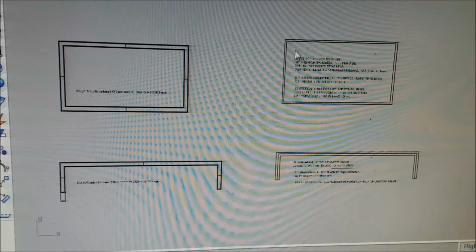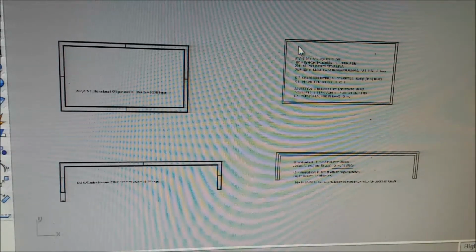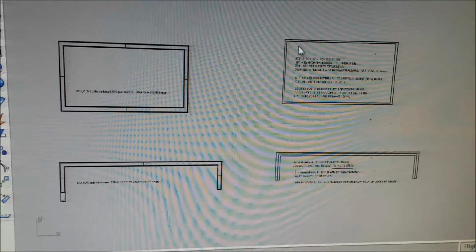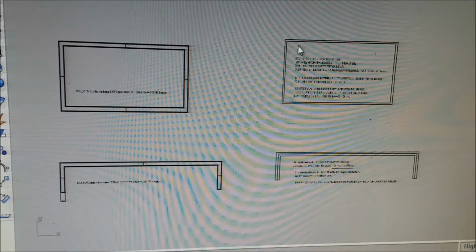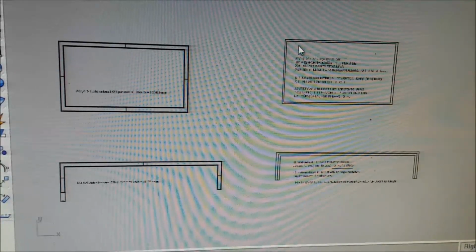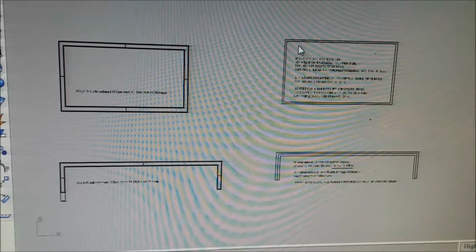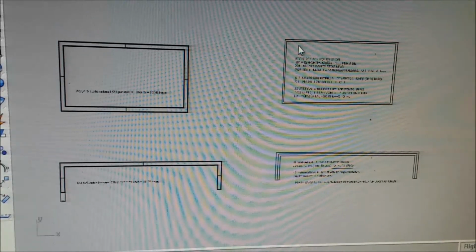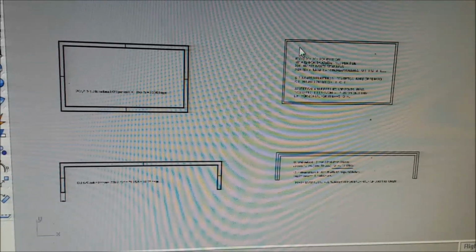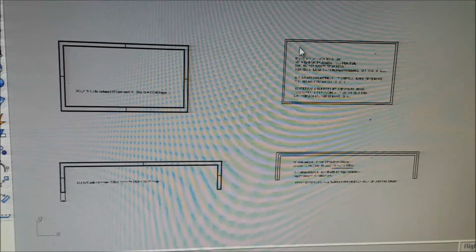If you start early enough, it's still daylight to get it finished at 80 bags on one bag mixer. We've got to hustle. About 84 is about our outer limit, and if it goes over that, we figure another way to do it. If he hits 96 or something like that, that's not doable in a day. Even pre-staging materials to keep from working your workers half to death on the pour day, that's just about as far as you're going to get.